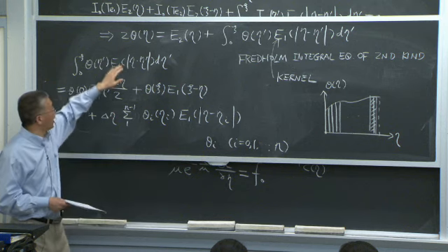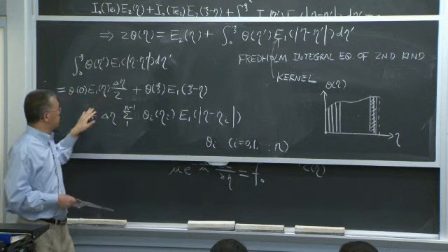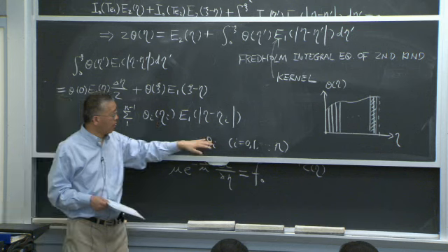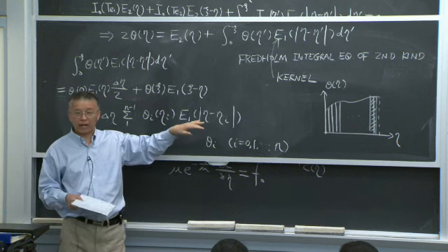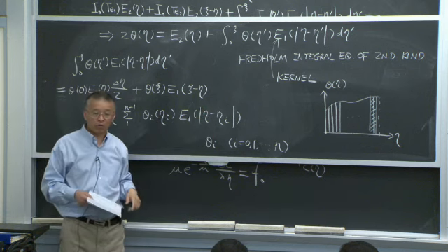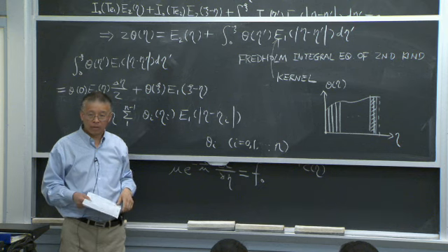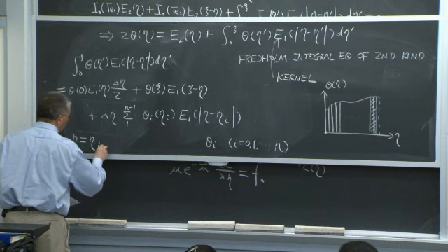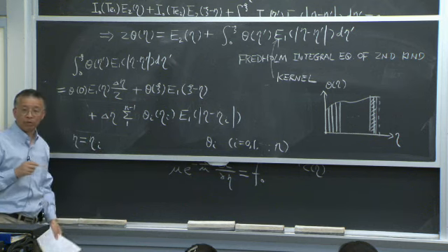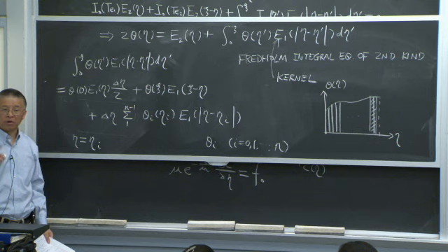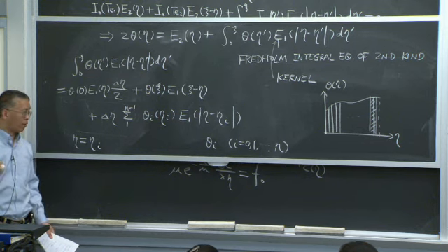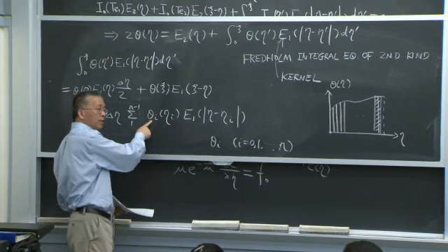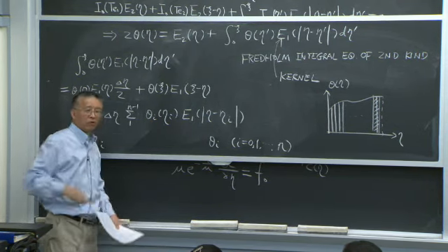You let your eta equal 0, delta eta, 2 delta eta, up to the total n points. So you set your eta equal to eta I. That's the discretization point. And then you'll get the n plus 1 numerical equations. And with that, you can invert the matrix to find what your theta I is.